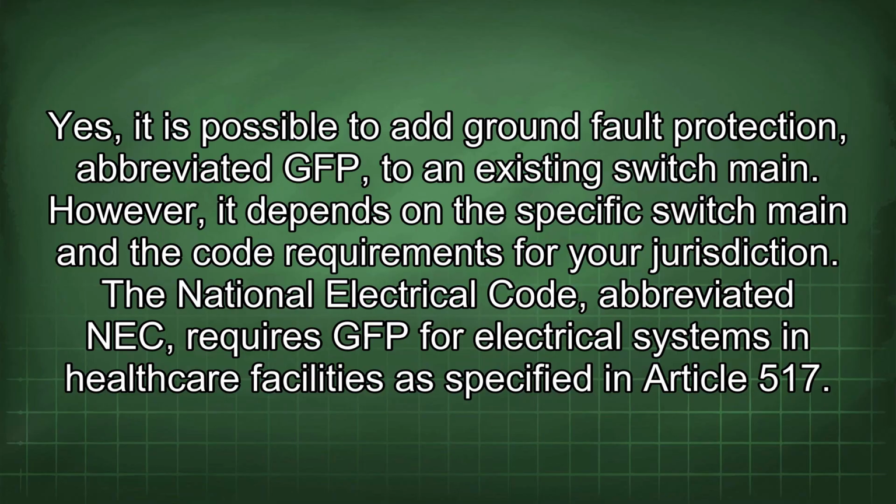Yes, it is possible to add ground fault protection, abbreviated GFP, to an existing switch main. However, it depends on the specific switch main and the code requirements for your jurisdiction. The National Electrical Code, abbreviated NEC, requires GFP for electrical systems in healthcare facilities as specified in Article 517.